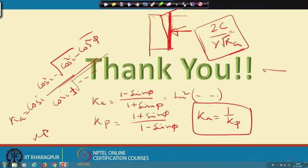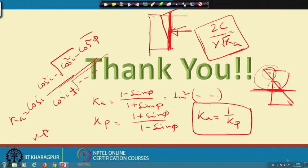How have we visualized this? The pressure diagram is like this, and this is the negative pressure. Because the total of this negative and the total of this positive cancel, it becomes 0. That means up to this depth the net effective pressure on the wall is 0, so up to this depth we can cut without any support. So you have to multiply by 2 to get the actual depth. This is the way we have done it.